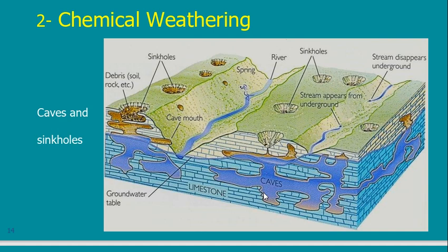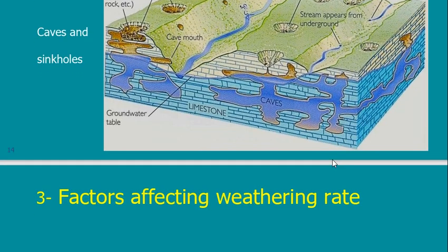Of course, it depends on the region. Is there rain? If limestone is found in a very dry condition, it will be a good limestone. But limestone with water means that it is possible that it would be disintegrated in some places, and caves are there. Caves mean that if I put my building on top of it, it will fall down. You remember the photo of the building in a place called Guatemala? I showed you at the beginning of the course.